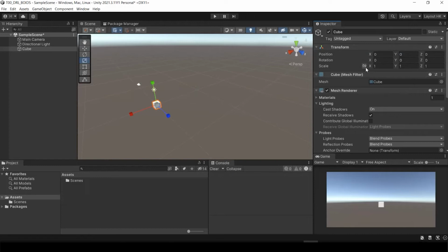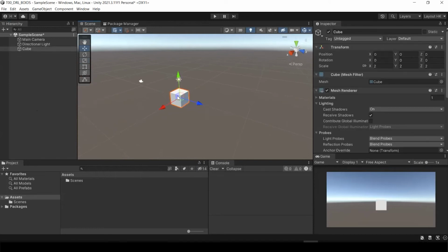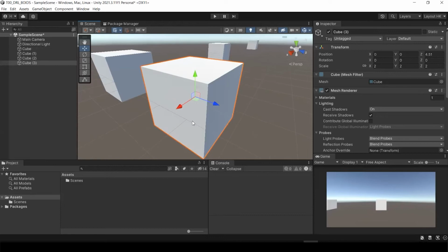And then you can see here the link button, so now you can change the scale. To copy the object, just click it and press Control D to duplicate, same as Maya again. Of course, you can do Control C and V, but I love to use Control D. To focus on the object, like zoom selected, F is just zoom focus.